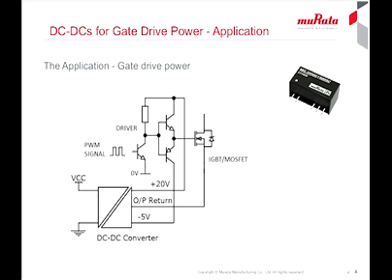The slide shows a simplified driver circuit for a MOSFET with its gate driven on to +20 volts or off to -5 volts, controlled by a PWM signal. The DC-DC converter shown is providing the power for the driver, and it also provides isolation from the supply powering the DC-DC, labeled as VCC, to the switched voltage. A complete circuit for sure would have capacitors on the power rails to provide peak currents, and there will usually be protection and fault monitoring circuitry around the gate.